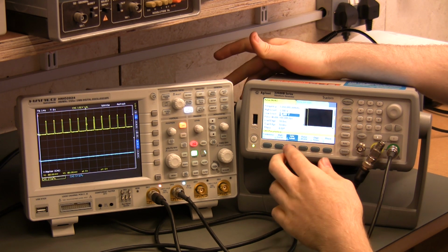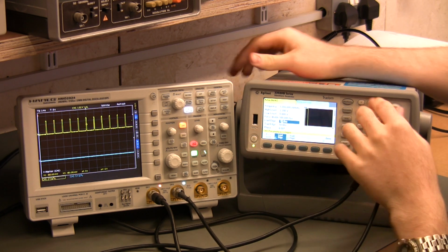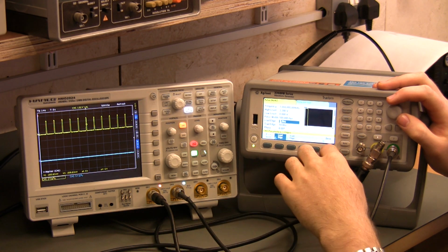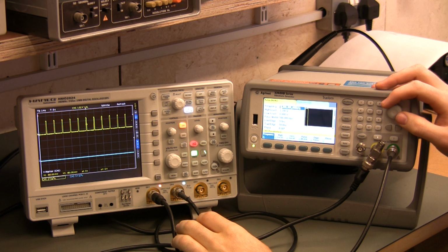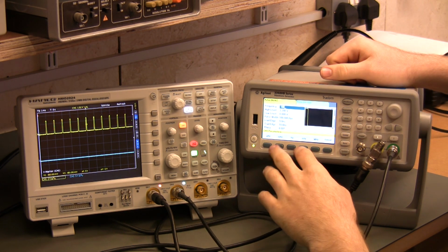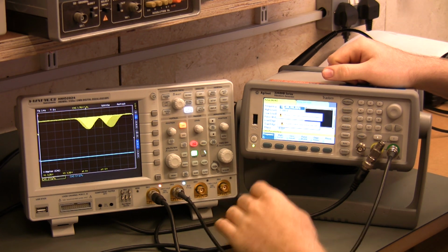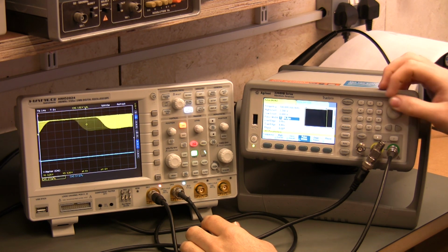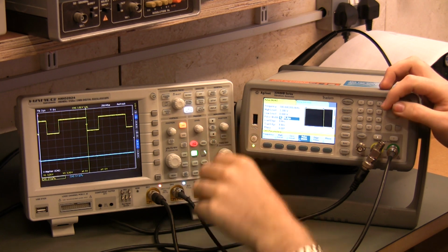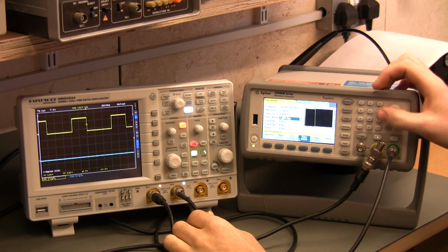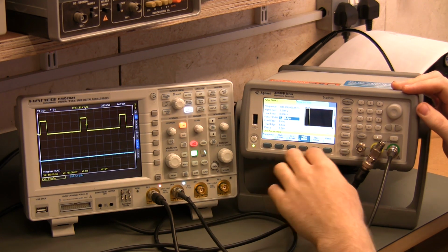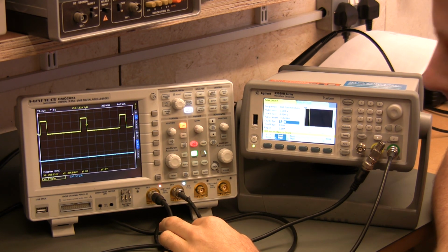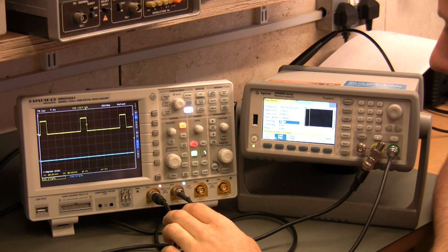And right, so obviously you've got nice and easy. We can also do things like control the edge times. What can we actually go down to here on this? Edge time set to minimum of 9 nanoseconds apparently. I suspect though, let's take that frequency up a bit. And pulse width, may have to drop correspondingly on that. That's what we're getting on the scope there. There we are, nice that, and okay, we seem to be hitting an actual sort of minimum rising and falling time of 8.4 nanoseconds there.